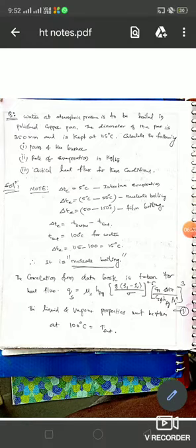Now, under what category does the given problem come, that we need to see. Simple. The surface temperature minus saturation temperature. Surface temperature is 115 degrees Celsius minus saturation 100 degrees Celsius is 15 degrees. This 15 degrees Celsius is between 5 and 50 degrees Celsius, and the type of boiling is the nucleate boiling zone into which it is coming.